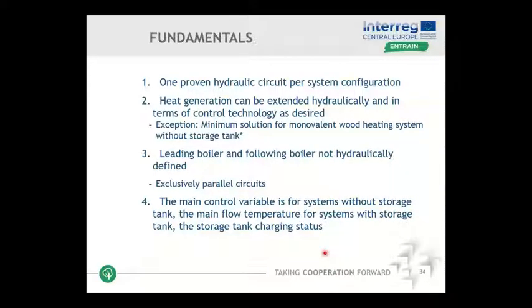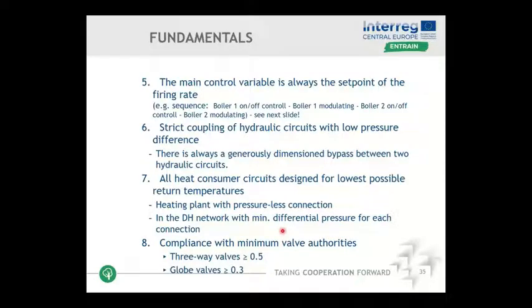But we want to operate our boiler steadily, no immediate load changes. This means we need a storage tank. I mentioned that already. But this is only working if the storage tank is doing load management. This means the main control variable to set the boiler load is the charging status of the storage tank. This is why we need 5 measurement points in the storage, for example. This is why we need a control strategy for the boiler. This is defined in the standard hydraulic solutions. We will not be able to go into detail here and discuss these concepts.